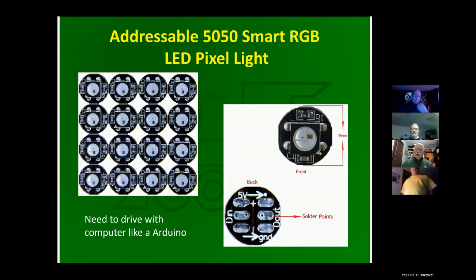And so you can see here, well, you can't see until I move the cursor. This is what's called the data bus. It comes in and feeds the next one, and if the instruction relates to it, it executes it. If it doesn't, it passes it on. And here are your voltage lines, 5 volts in and the ground, and so they're all linked together.